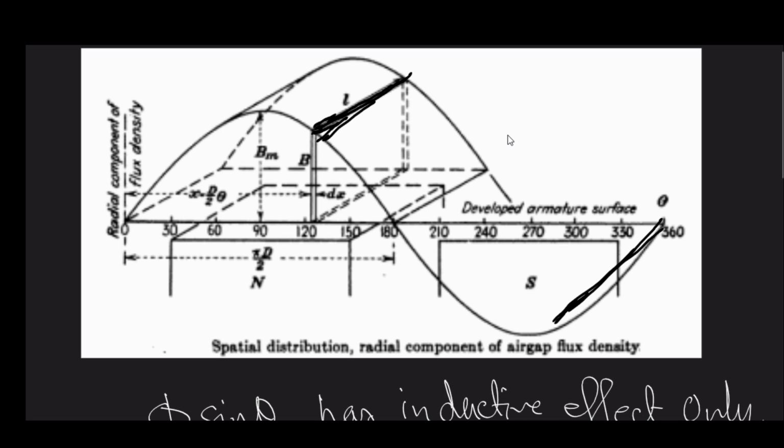You will place one more conductor here, and here will be another conductor. So, depending on the number of conductors, you keep on placing conductors in the same slot. The two sides of your coil are all full pitch, meaning a concentrated coil, and they are exactly 180 degrees electrically phase apart, right?